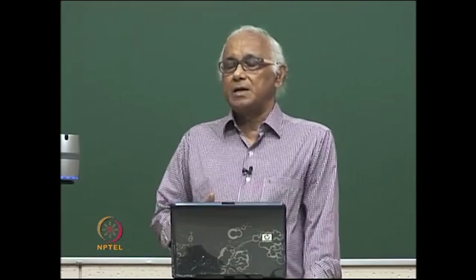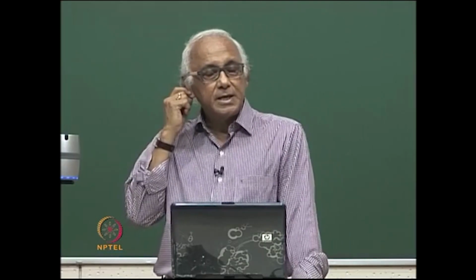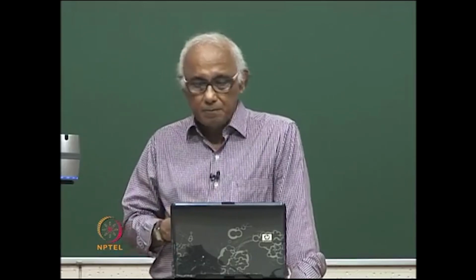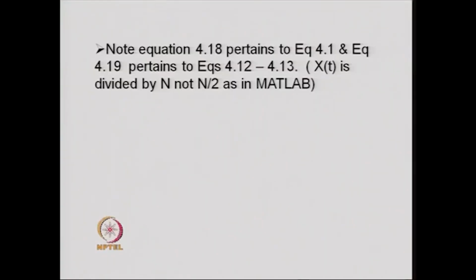So, since a stationary process is characterized by a unique mean square value, the power spectral density function constructed in this fashion provides a good estimate of the input for the random vibration analysis, or the spectral analysis, in particular spectral analysis of structures.